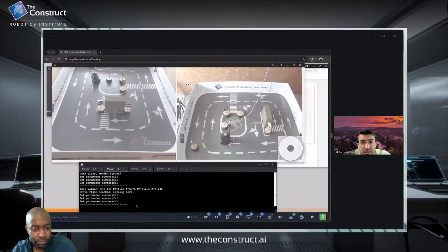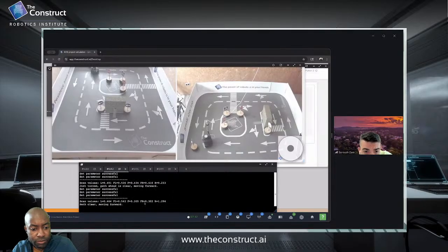And with those 16 conditions, we can just calculate. I think maybe the best navigation algorithm would be to find which of those 16 directions has the highest value, and then rotate in that direction and go forward. And if there is not a big difference between the directions, prefer to go forward. Here also I calculated in my code that at some point front right is like 0.302.